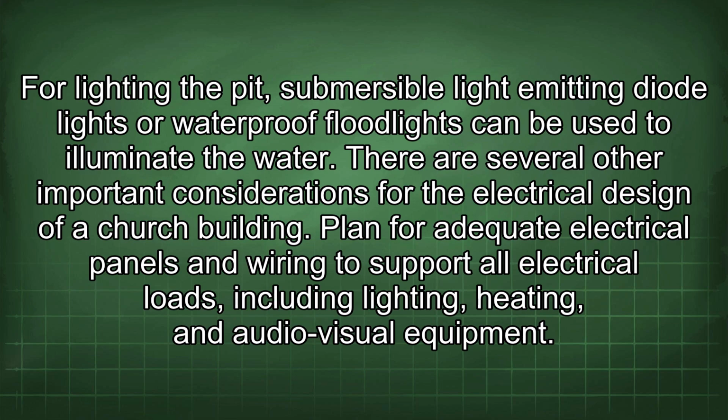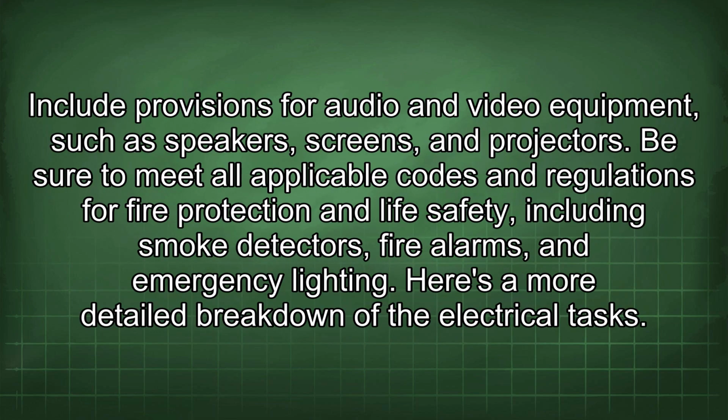There are several other important considerations for the electrical design of a church building. Plan for adequate electrical panels and wiring to support all electrical loads, including lighting, heating, and audiovisual equipment. Include provisions for audio and video equipment, such as speakers, screens, and projectors. Be sure to meet all applicable codes and regulations for fire protection and life safety, including smoke detectors, fire alarms, and emergency lighting. Here's a more detailed breakdown of the electrical tasks.